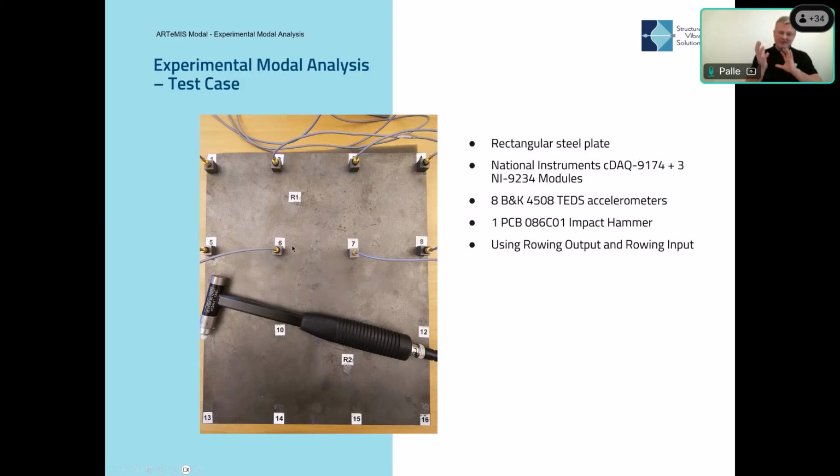So they have a kind of machinery that is very difficult to get in with the hammer and then excite all these points where the mode shape should be known. It's easier just to excite a few places. This is a cylindrical structure that we designed it for. So you have to impact in one direction and perpendicular to that later on. And then you can move around with a block of sensors, which is easier in this case. So for accessibility reasons, this was made in this way.